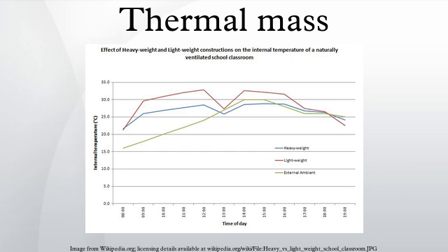During the day heat is gained from the sun, the occupants of the building, and any electrical lighting and equipment, causing the air temperatures within the space to increase, but this heat is absorbed by the exposed concrete slab above, thus limiting the temperature rise within the space to be within acceptable levels for human thermal comfort. In addition, the lower surface temperature of the concrete slab also absorbs radiant heat directly from the occupants, also benefiting their thermal comfort. By the end of the day the slab has in turn warmed up, and now as external temperatures reduce the heat can be released and the slab cooled down ready for the start of the next day.